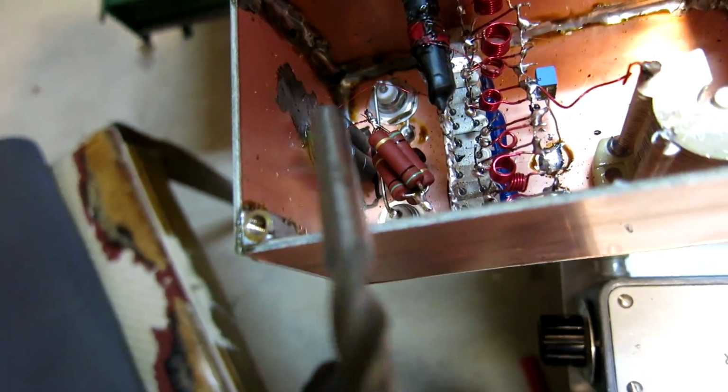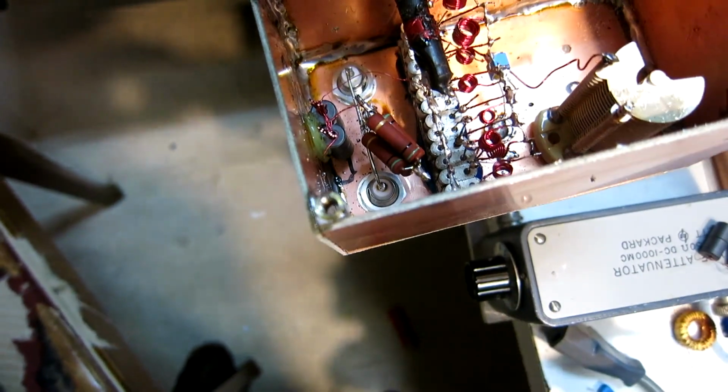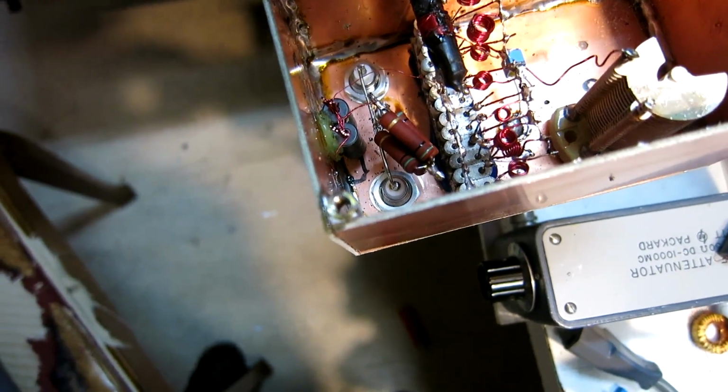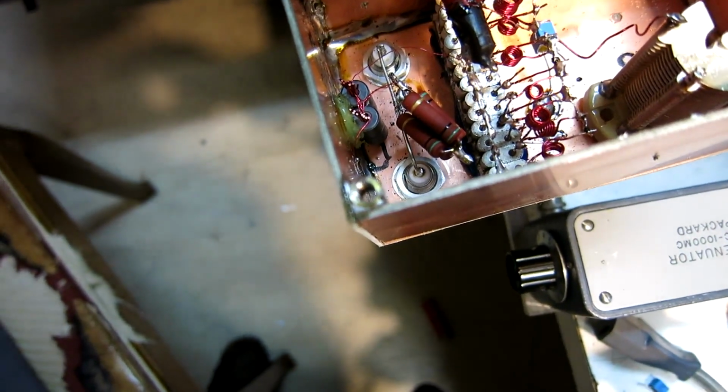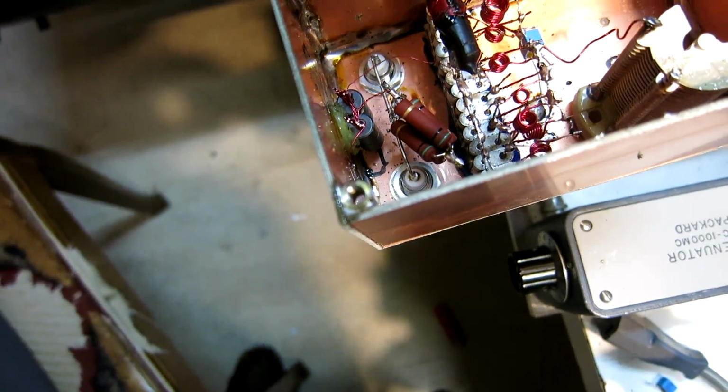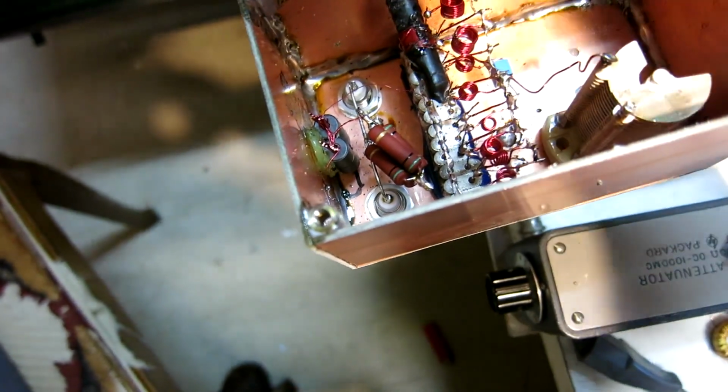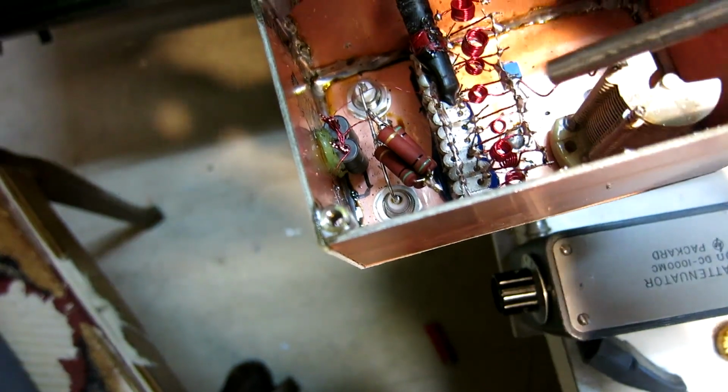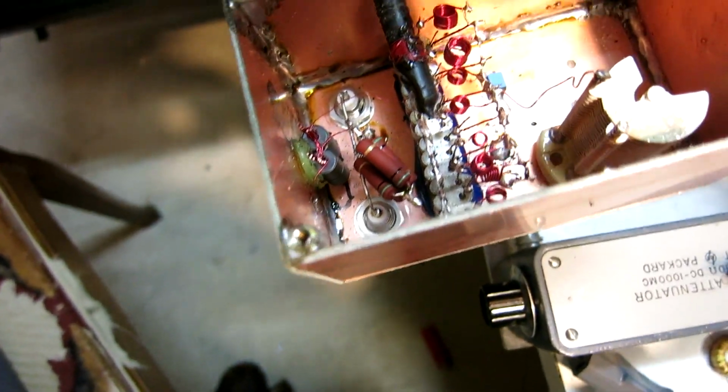Well, here you can see this one. I want a small leakage inductance, so I have pushed copper wires into the holes of the ferrite to fill it with copper completely. Then I have a 50 ohm resistor. 4 50 ohm resistors connected to give 50 ohm, but to tolerate 4 watts. And this coil cancels the parallel capacitance of all the crystals.